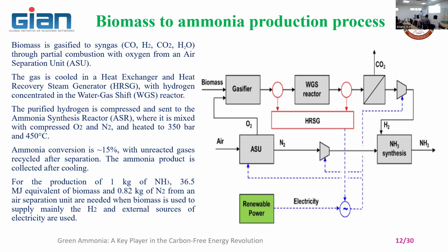Then you need to do the energy content of the biomass by using a bomb calorimeter. So bomb calorimeter is a device used for measuring the calorific value in terms of kilojoules per kg or megajoules per kg. It's a constant volume bomb. This facility is also available in our laboratory. If anybody wants to explore it, you can contact us. We can support. The bomb calorimeter is for measuring the calorific value of both solid and liquid.